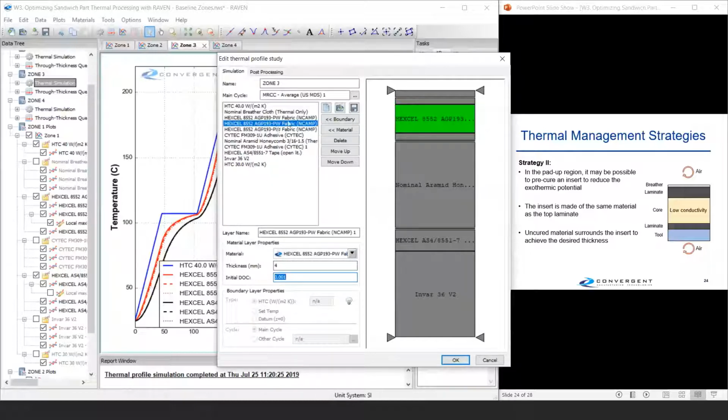And so I pre-ran just a 0D analysis with the default cure cycle. That gets you to 0.88 final degree of cure after that. So I'm going to use that as my assumption here. You could put in 1, I'm going to put in 0.88 to be somewhat realistic, and you could pre-cure this part, you could even partially cure the insert and check and see. But in this case, I know that the initial degree of cure is going to be about 0.88.